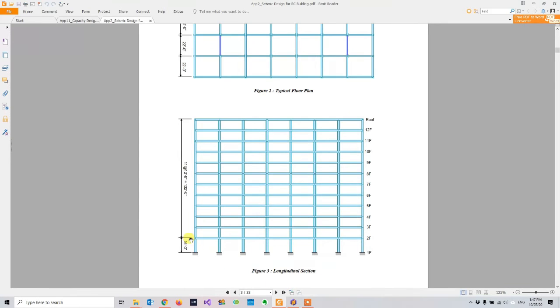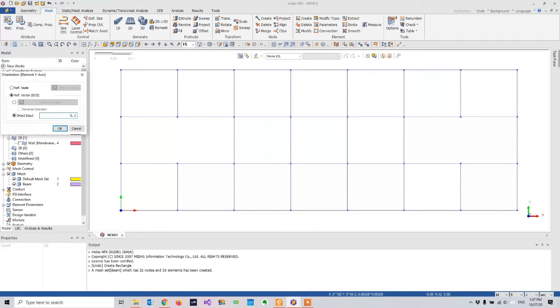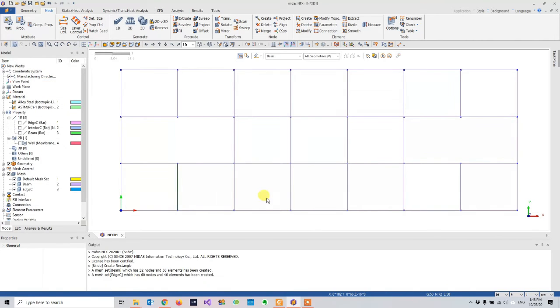All right, so I'm going to extrude this point into the Z direction, and here I have 16 feet. All right, so yes, feet, let's go to feet. Nice, we have 16 feet, which is in the minus direction of the Z here, and this is the edge column. All right, so let's make the name of edge column. Oops, yeah, of course, we have to realign the coordinate system of that particular extrusion, and you should be able to preview the edge column.